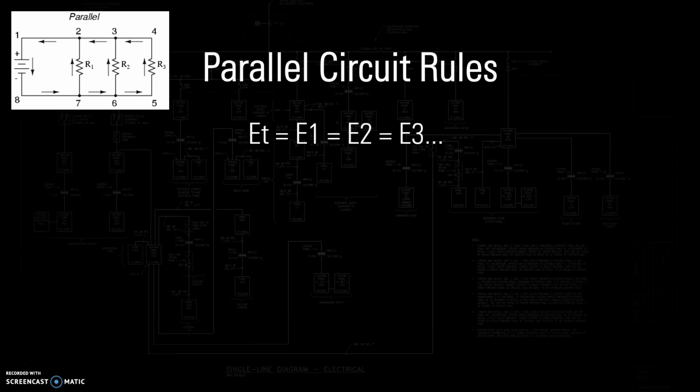Total voltage in a parallel circuit is equal to the voltage of element 1, and element 2, and element 3. Again, that goes back to this direct connection from any element back to the source. That's another reason why we wire everything in parallel in the field. If I wire up a bunch of lights in series, they're all going to have some fraction of my source voltage. If we wire in parallel, every single load gets the intended voltage, usually, let's say 120. Every one of my lights, if these loads are lights, gets 120 volts, regardless of the other ones.